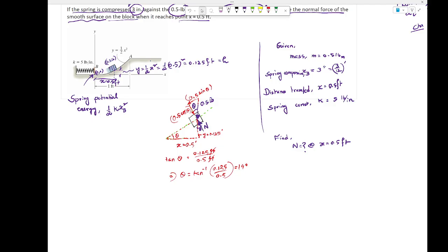So now, anybody remember from the last exam, actually from even the first exam, what is the normal direction acceleration equation? There are two different accelerations, right? An and at. An is the normal direction. v squared over rho, right? What is rho? Radius of curvature. Do you know the equation for rho? You may have forgotten, but that's a complex one, right? It's a second order derivative that you have to deal with.